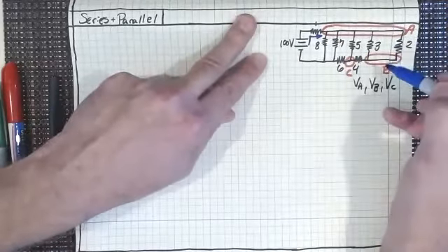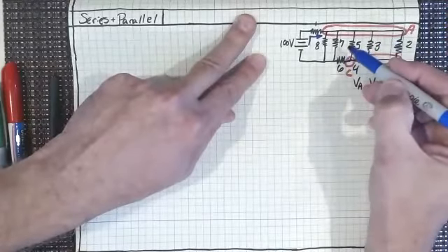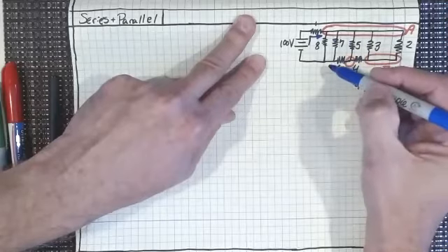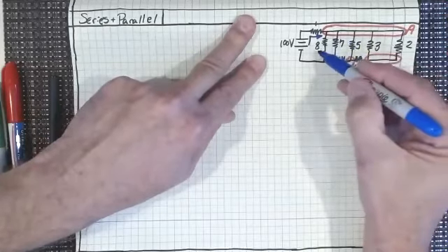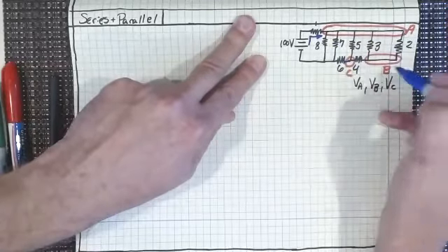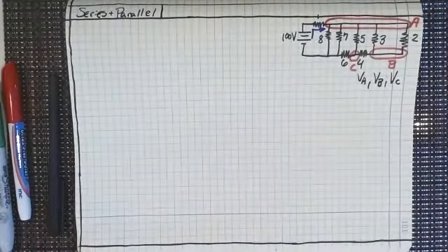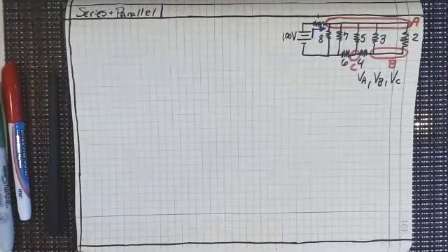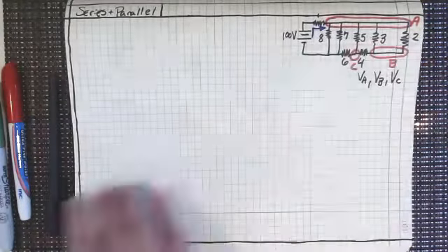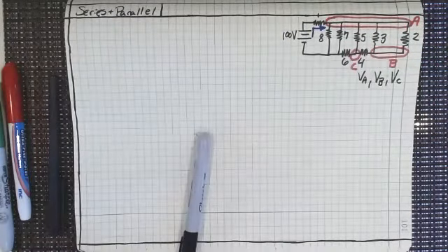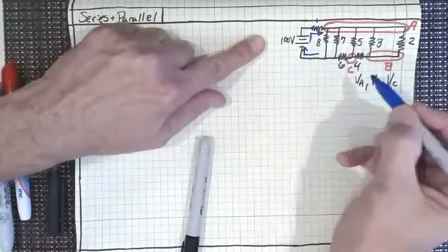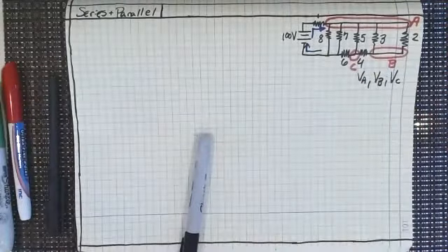And we can do that by figuring out voltages at different points, and then looking at the resistors that are going through those different voltages. We look at a voltage differential plus the value of the resistor, and we can figure out what the voltage drops are and everything else. Very straightforward process. So that's the first current, and then the currents are going to change, of course, as they go around. That first current, of course, is also the current that's coming back in to the power supply, isn't it?